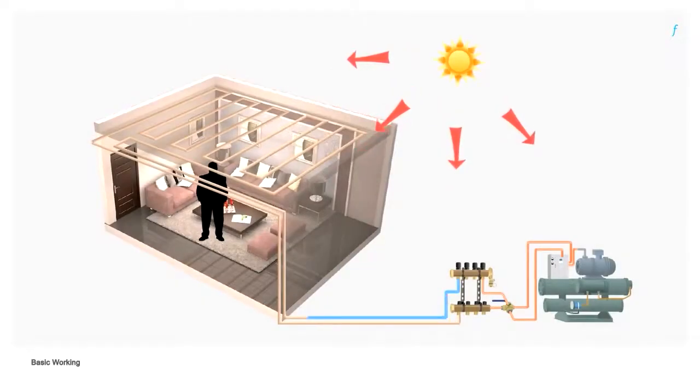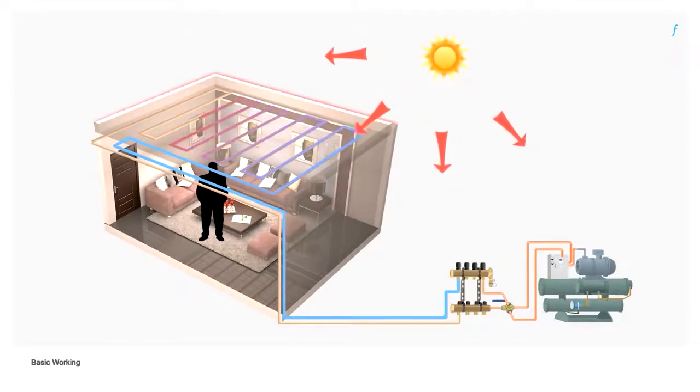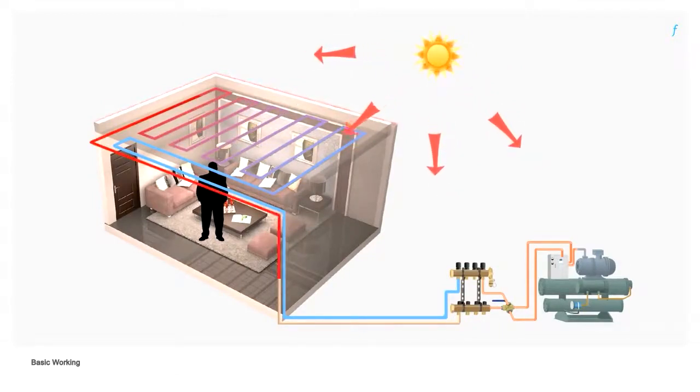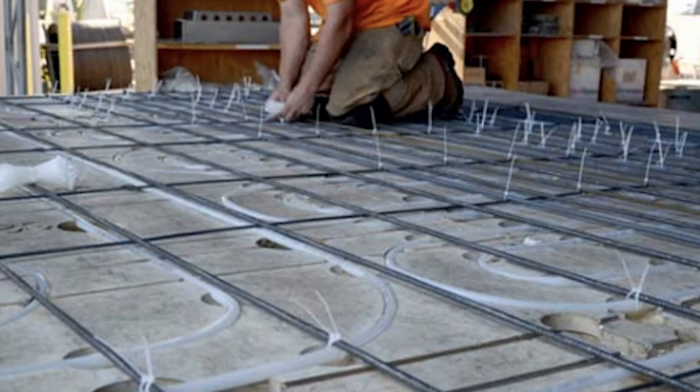The first step in solving the mechanical problem was to reduce the forced air duct requirements by utilizing the thermal mass of the concrete and providing a radiant cooling system in the ceiling. This was achieved by placing coiled loops of chilled water PEX tubing into the soffits and daylighting them in manifolds that would be accessible in the above-the-floor slab. The tubing was set up in circuits that coordinated with different climate control zones. The chilled water radiant ceilings dramatically reduced the HVAC demands, but space was still limited.